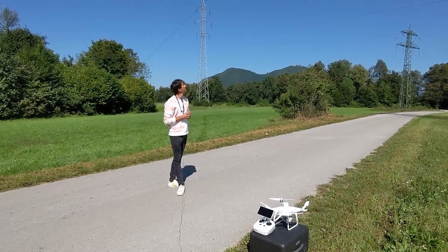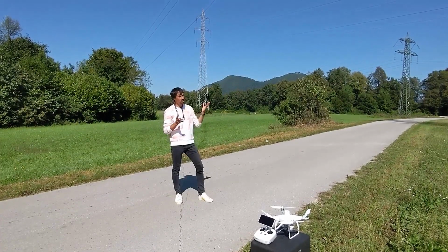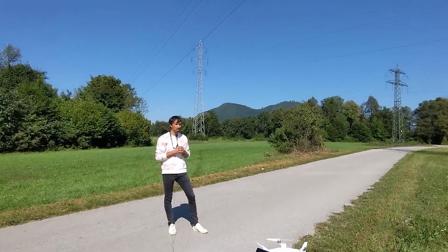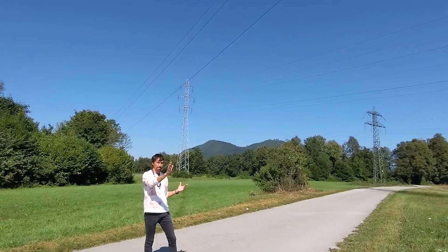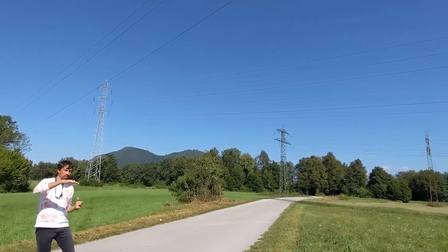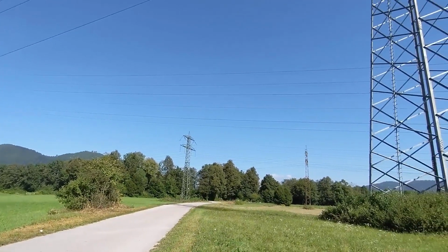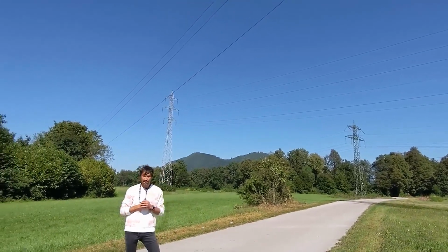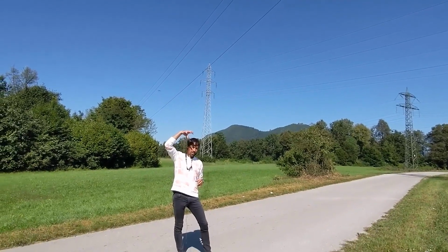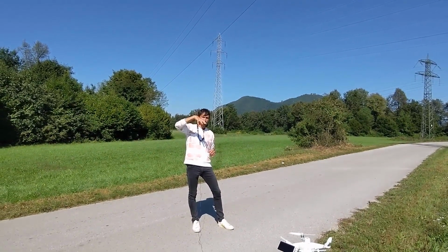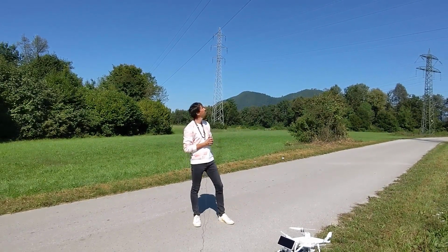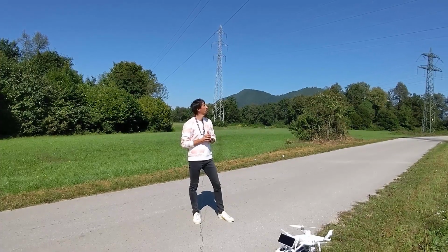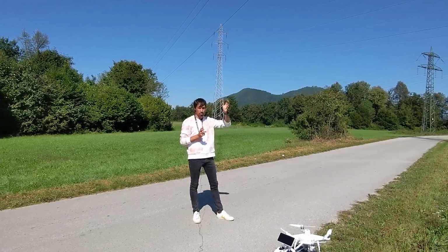What's interesting here, we need to fly high enough not to hit any power lines. Before, we always advise you to inspect the terrain a bit, to see if the terrain is going up and down. And I would suggest you fly for that kind of objects at 80-meter height with the camera not turned fully down, so nadir images perpendicular to terrain, so the flying height 80 to 100 meters. If you have even higher poles, then go even higher.